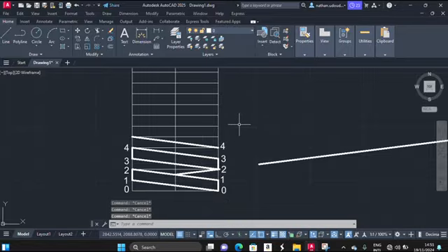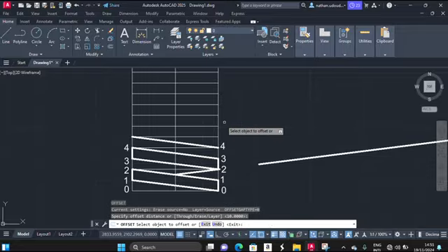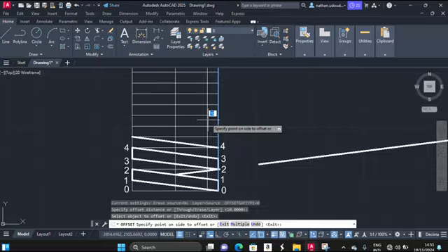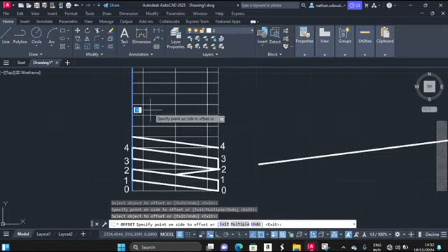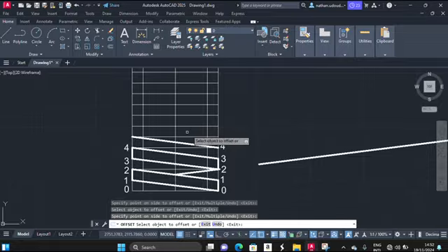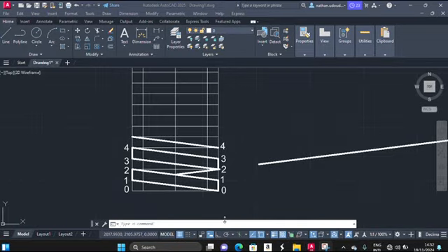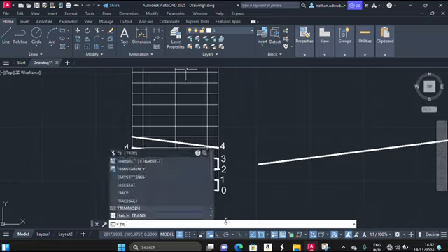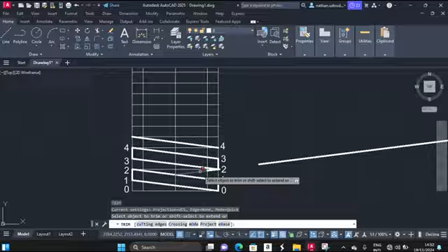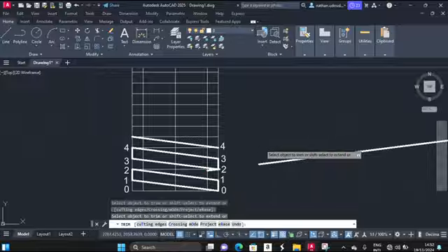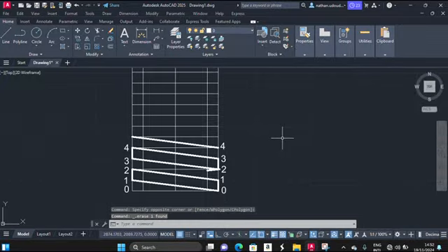So now you also take the offset distance of 10, O, enter, that's 10 from the pitch. The pitch is 20, so 20 divided by 2 is 10, so we also have 10 at this point here, okay. So now you can take your trim command, TR, enter, and then you have that. So SK, enter, so you can delete this.